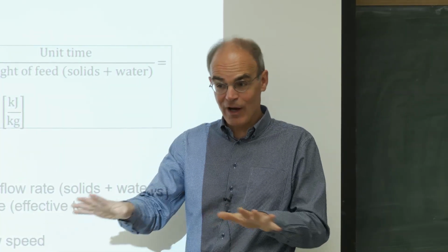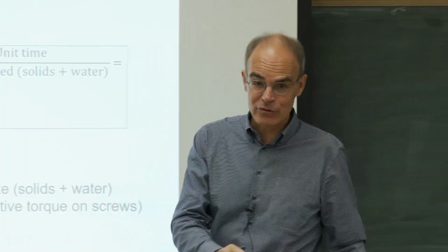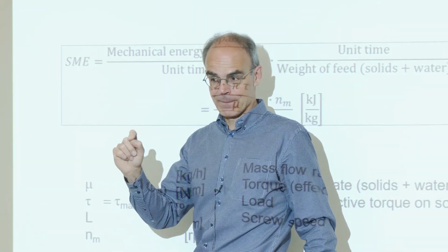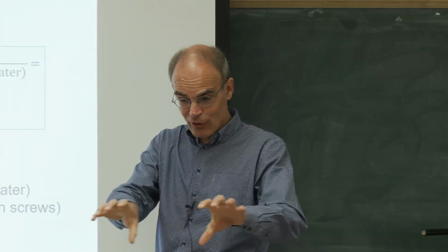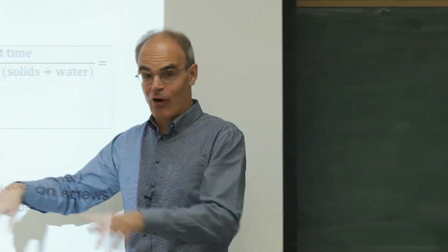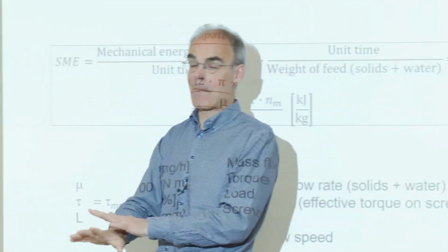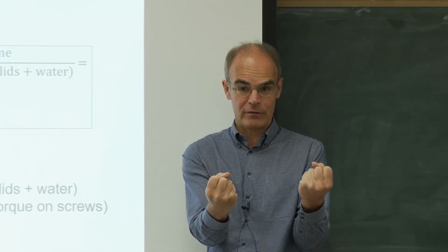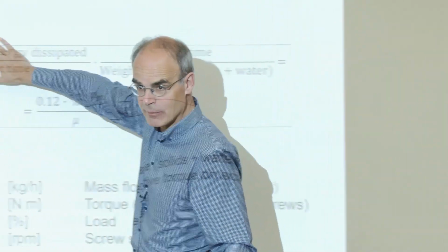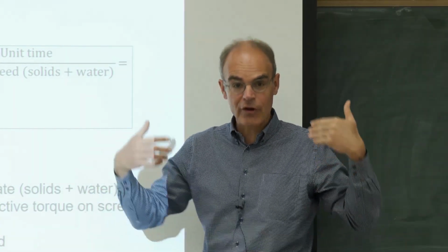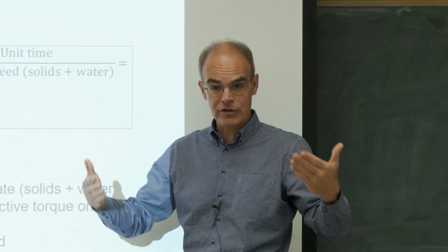There's a difference between low and high water content extrusion. In low water content extrusion, I'm generating an enormous amount of heat by the shearing. Effectively, only in the startup time do you heat the extruder barrel over these heating elements. At some moment, they all go over to cooling mode because you're just generating massive amounts of heat by shearing that high viscosity material. So that energy, as you shear it, all these molecules get sheared and they resist that, and as a function of the viscosity, a lot of the heat is dissipated. So your product starts to really heat up.